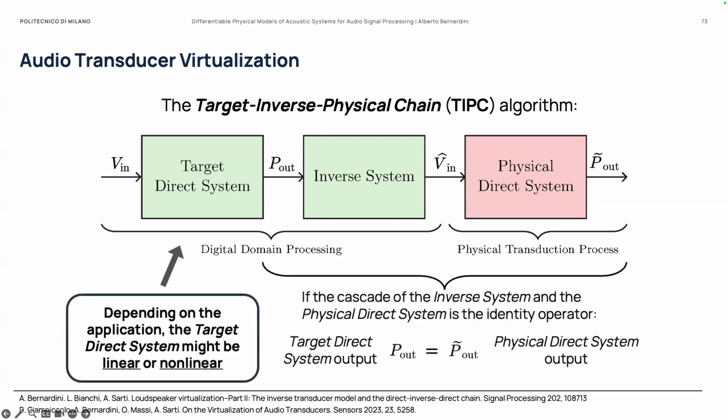In this definition, are we talking about a digitized version of the physical system, or are we talking more about blocks? Exactly, blocks. For instance, this is the inverse circuit model, like the one we have just seen of the MEMS loudspeaker. This is the actual real MEMS loudspeaker. If this is exactly the inverse of this, I can impose the behavior of a target loudspeaker, which might be a virtual one, one that I want, like the linear version of the analog one, or the differently equalized version of that, and so on and so forth.